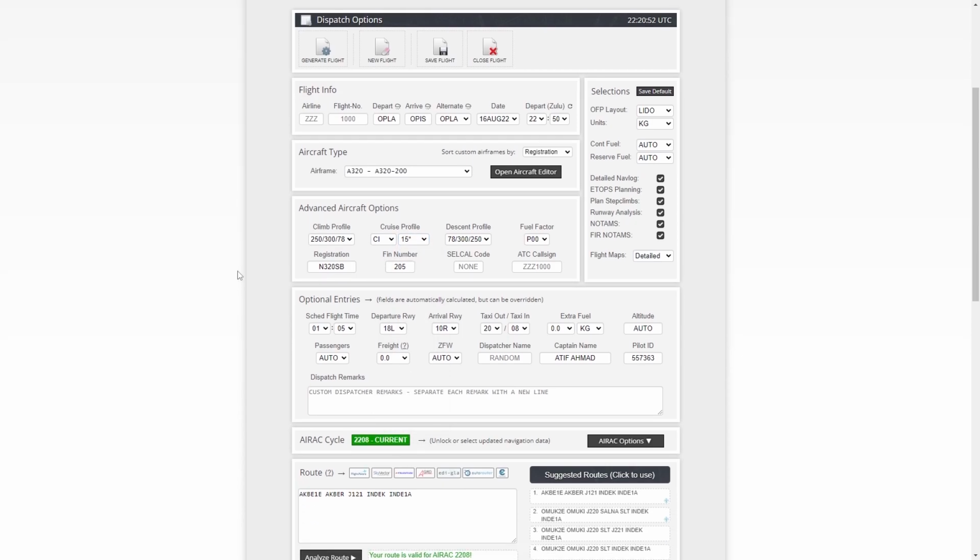It's actually a number which is used to calculate the fuel burning rate. The smaller the number, more fuel is burned, but the plane goes at a higher speed. The bigger the number, less fuel is burned, and the plane's speed is slow when autopilot is activated. So this is used by the airlines to basically manage their fuel and to save their cost.